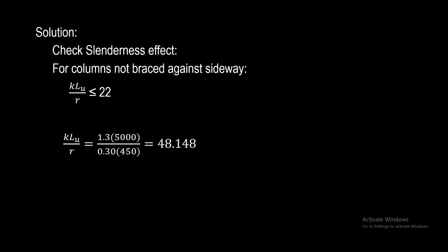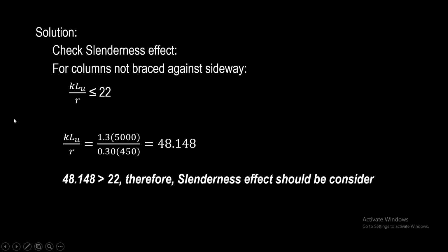Comparing it to the criteria, 48.148 is greater than 22. Therefore, we should consider the slenderness effect. In short, this is a long column problem.